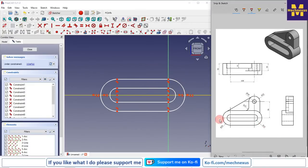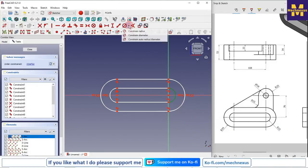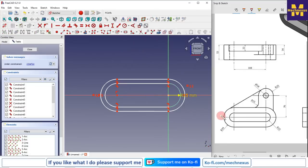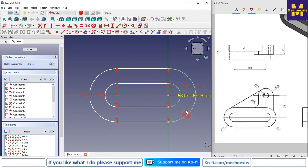So here if we zoom it, the inner one is R15, so I will select it and give the radius dimension of 15, and the outer one is R34, so I will select the radius and give it 34.